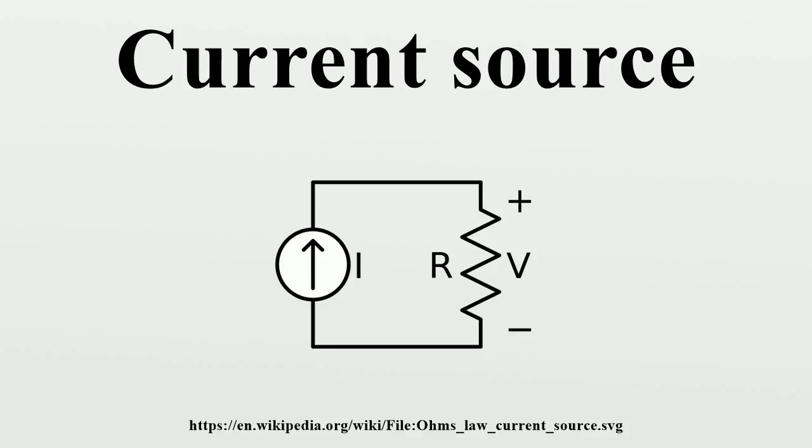This constant current source with emitter degeneration series negative feedback is also used in the two-transistor current mirror with emitter degeneration. Negative feedback is a basic feature in some current mirrors using multiple transistors, such as the Widlar current source and the Wilson current source. Constant current source with thermal compensation. One limitation with the circuits in Figures 5 and 6 is that the thermal compensation is imperfect. In bipolar transistors, as the junction temperature increases, the VBE drop decreases.